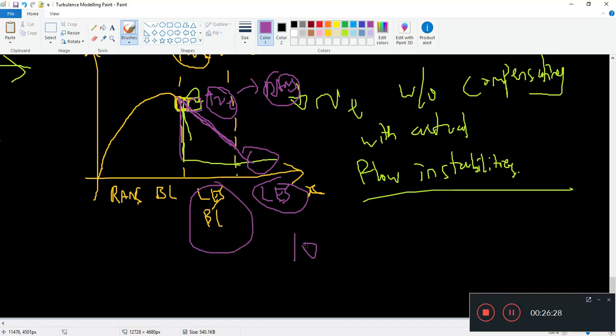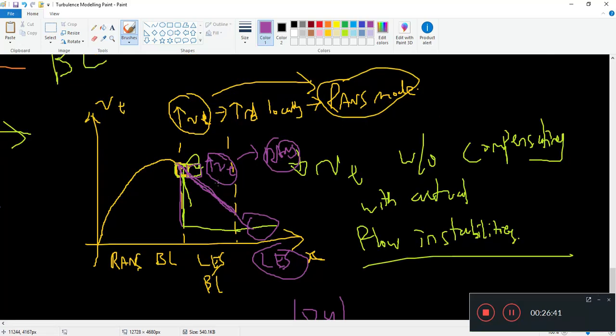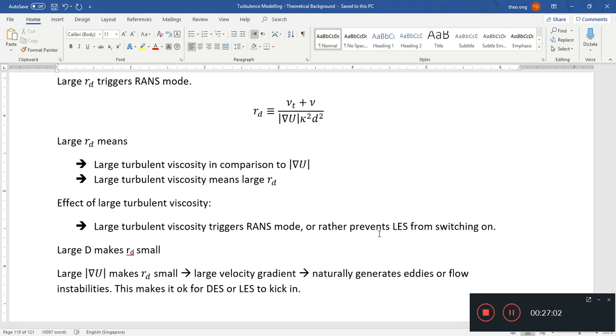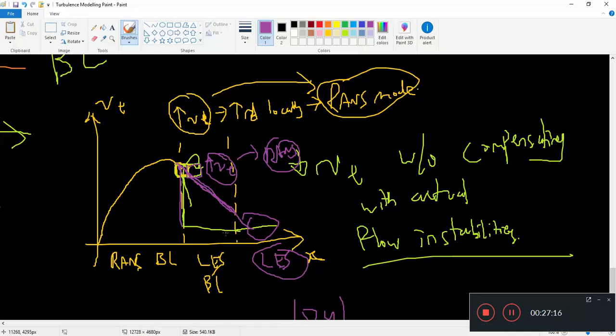Here you have, especially in the outer boundary layers, high amounts of shear, strain rate, so that you can generate your turbulence. So that makes it a more appropriate place to let go that nu-T and let DES kick in. So the long story short is that when you have high nu-T, it delays the onset of turbulent LES. Delays the onset of LES or DES. So that's why it's called delayed detached-eddy simulation, and this actually helps prevent the model stress depletion.